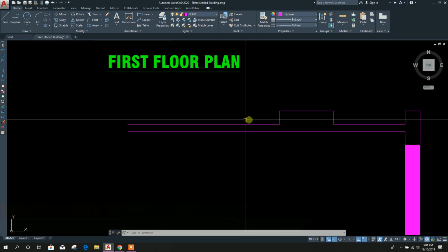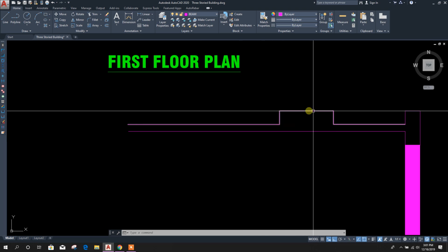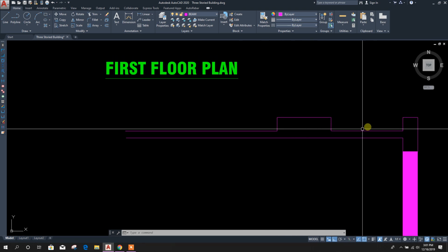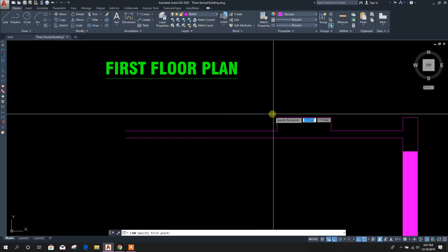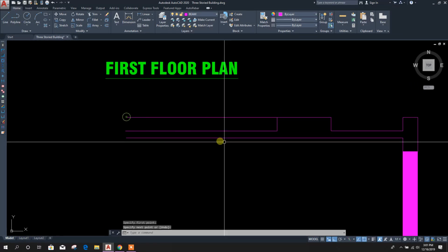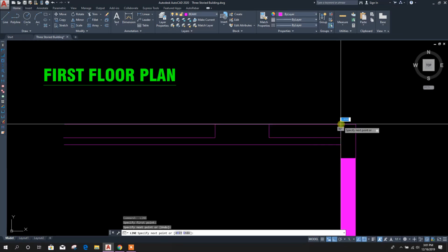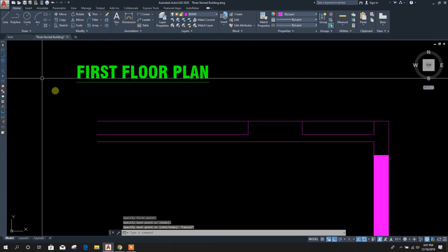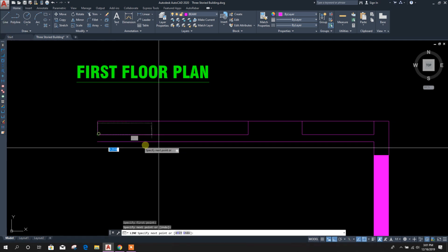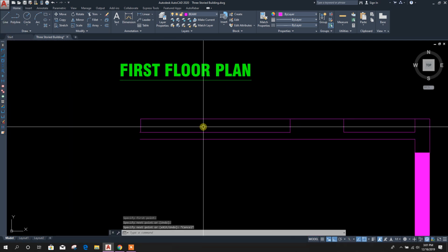At floor level, as we can see, there is offset. To remove this offset, what is done, this level we have to provide sand filling.